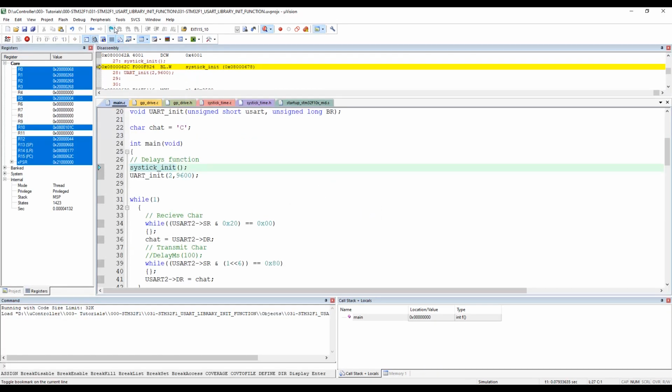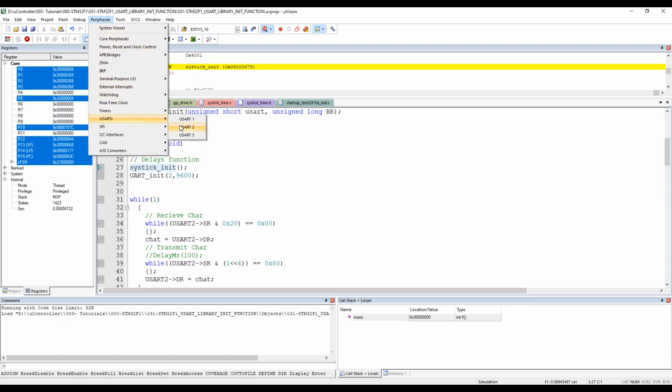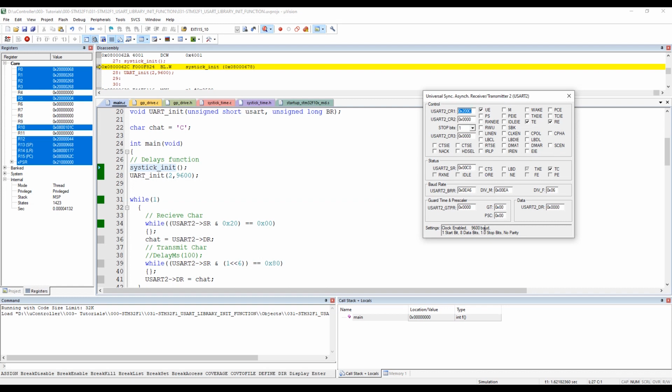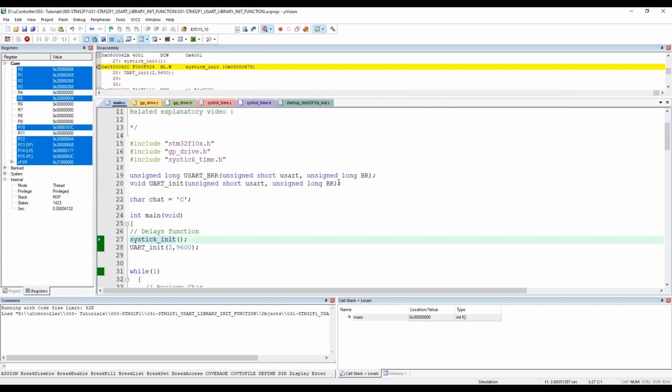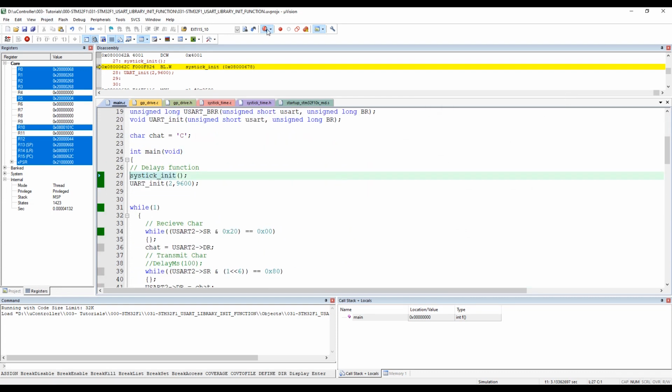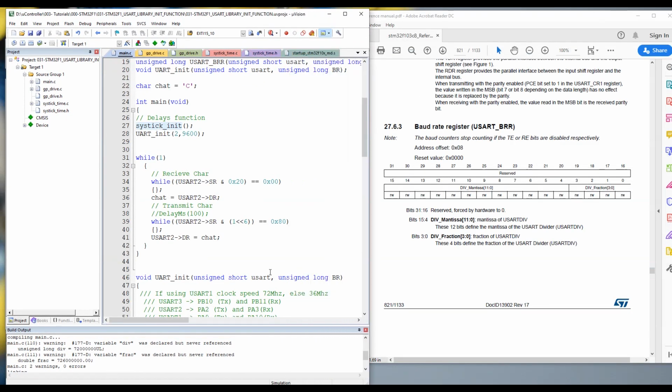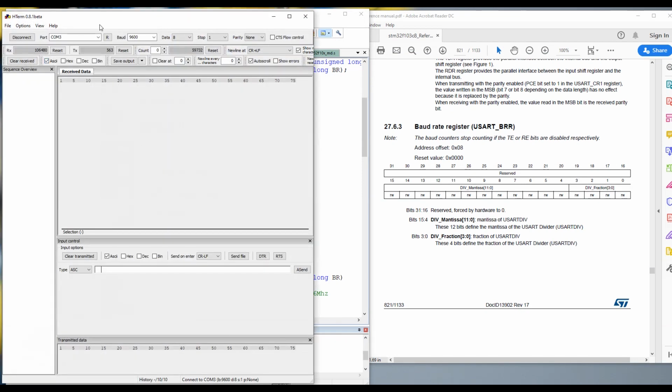Let's run. So we go to peripherals, UART, UART2. You can see here, that's fantastic. We have the clock enabled and a 9600 baud rate. Let's try another baud rate. Let's close the simulator and check whichever baud rate. Let's choose from the H term, this one, 115,200.